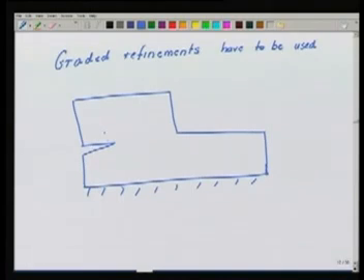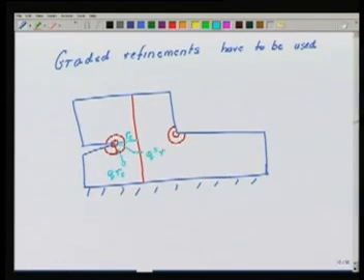Okay. So what I will do is, in the vicinity of these cracks, I will make rings. These are graded rings in such a way that the radius of the inner ring and the outer ring are related. So I take some characteristic distance, which could be, let's say, the distance from the middle line to this crack tip. So this is my characteristic distance, R characteristic. Then this outer radius will be some q times R characteristic, while the inner one is q squared R characteristic.